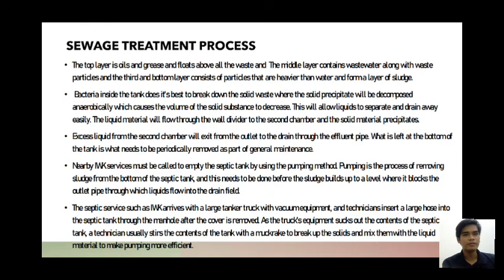What is left at the bottom of the tank is what needs to be periodically removed as part of general maintenance. Nearby IWK services must be called to empty the septic tank by using the pumping method. Pumping is the process of removing sludge from the bottom of the septic tank, and this needs to be done before the sludge builds up to the level where it blocks the outlet pipe through which liquids flow into the drain field.